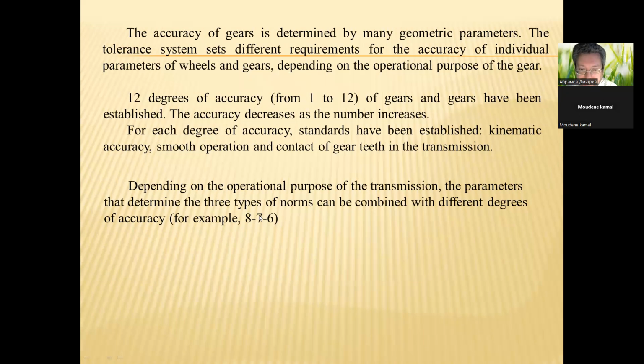8-7-6. In first place, it's kinematic accuracy: 8 is the degree of kinematic accuracy, 7 is the degree of smooth operation, and 6 is the degree of contact of gear teeth.